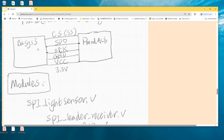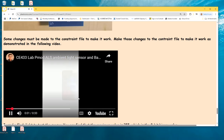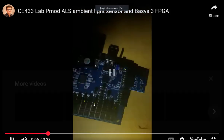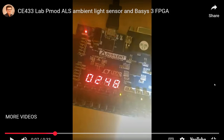And the light intensity values are read as binary values and can be displayed on the LED. So the LED shows the binary number of the 8-bit light intensity from the sensor, and it's also displayed on the 7-segment display as well. You can see the maximum value is probably 255, so you'll know that it's an 8-bit sensor, right?